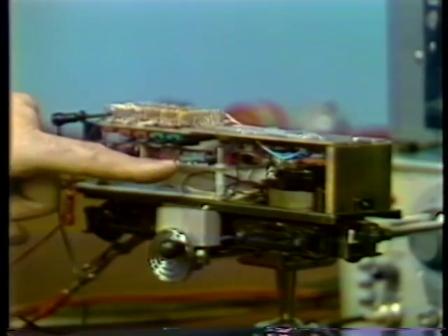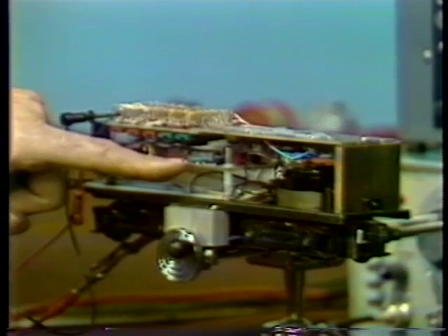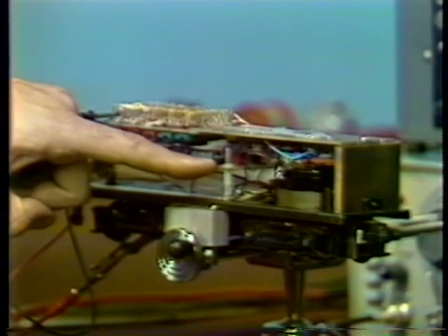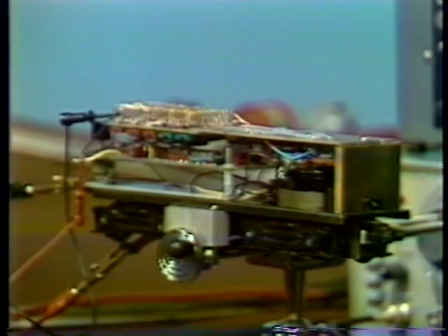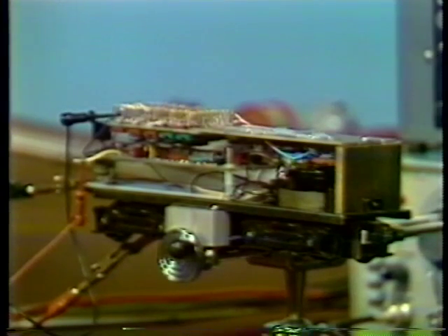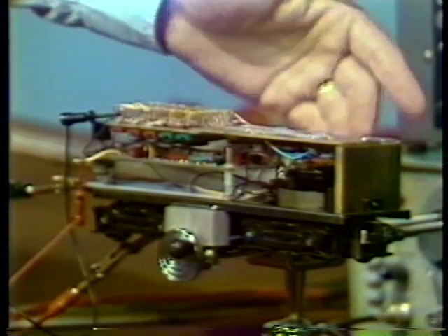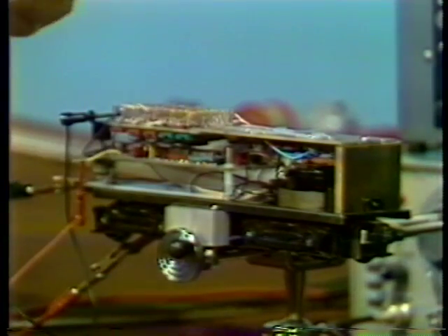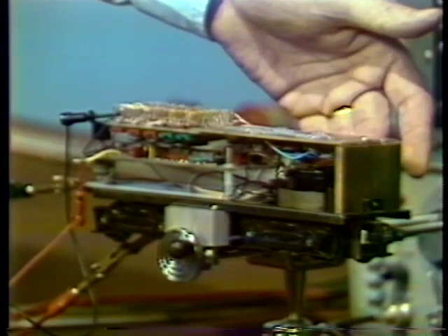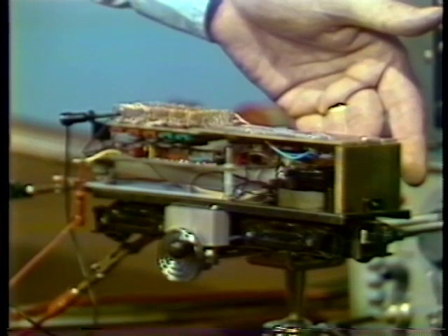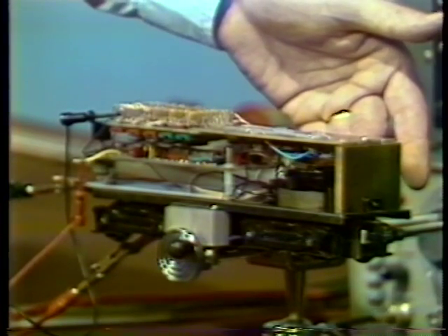There's also provision on this little board that, as I say, is really included only for demonstration purposes. I have a rough analog measure of speed available on that board. I have a one-shot that's triggered from the motor pulses, the pulses that are derived from the commutator spikes. I average the output of that one-shot. The one-shot multivibrator gives us a fixed width pulse every time we get a commutator spike. Those pulses are converted to standard amplitude and then averaged, go through a low-pass network that gets an average value for the pulse train. That average value is proportional to speed.